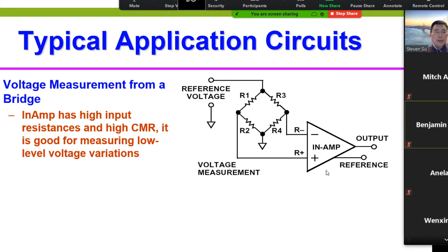So this is the common mode gain. You also have the differential mode gain. That means if you have a difference input, for example minus 1 at one input and 0 at the other, or minus 1 and positive 1, your output normally has a very big value, and this is the differential mode gain. You use the differential mode gain divided by the common mode gain, and you get CMRR.